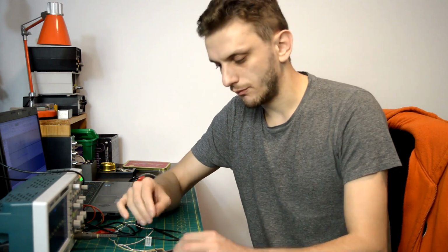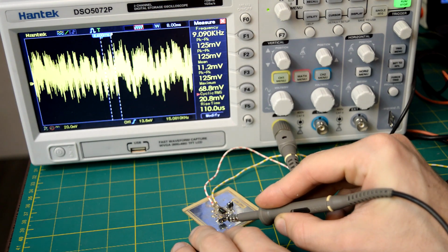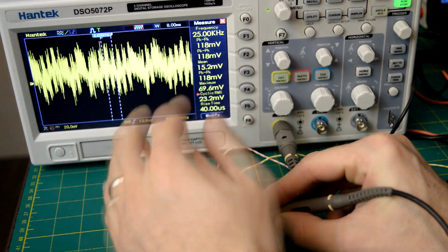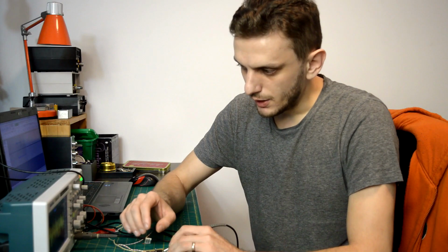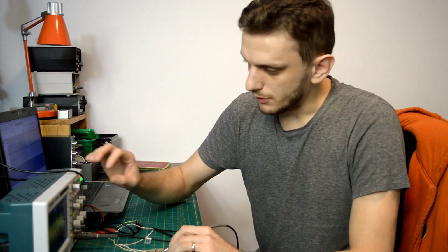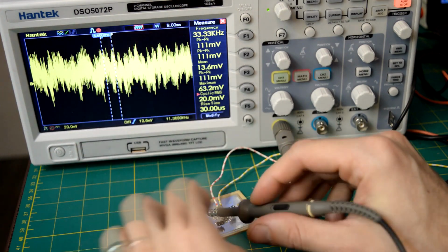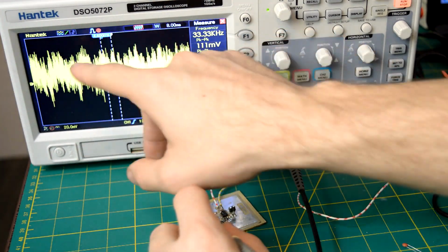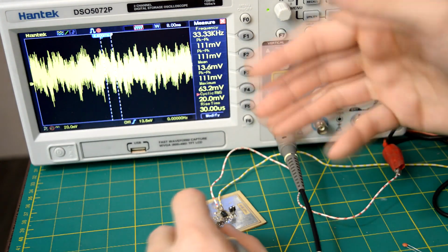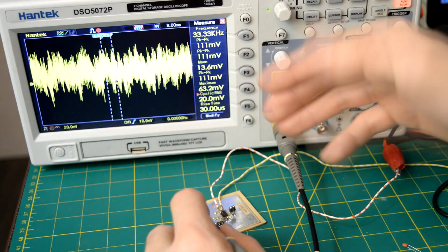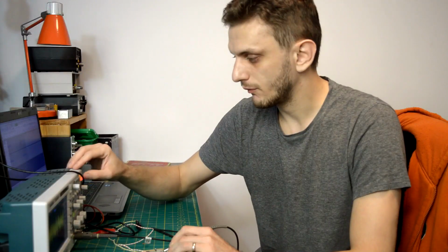So let's just see if this bandwidth reduction thing actually works in practice. And we can do that with the circuit we started with. So if we recheck again its output noise, we see the 100 something millivolt of peak to peak noise. But if we look at the waveform a bit more closely, we can also see that there's a lot of high frequency content in this. So we see a lot of very thin, very sharp spikes going through this waveform.